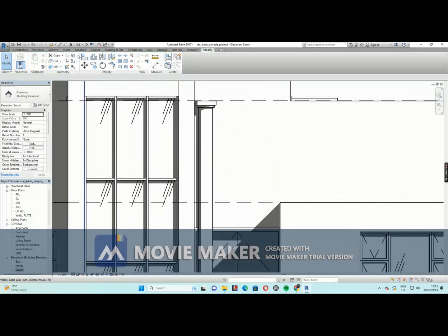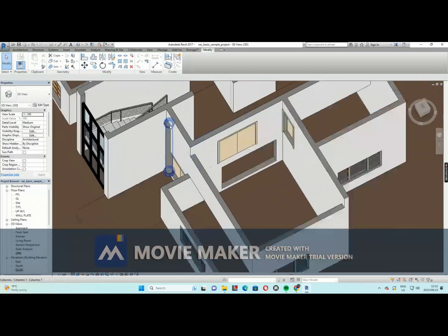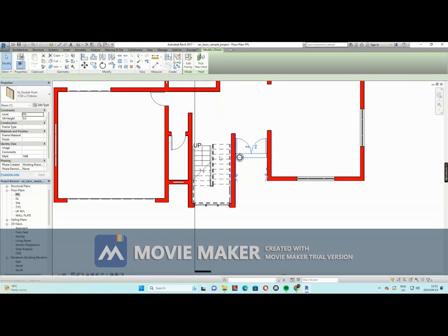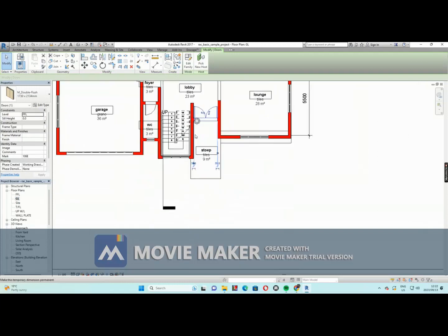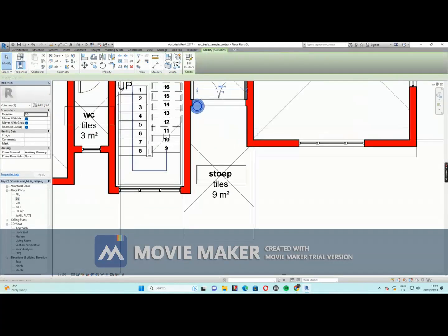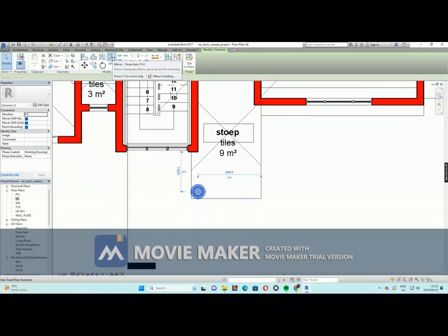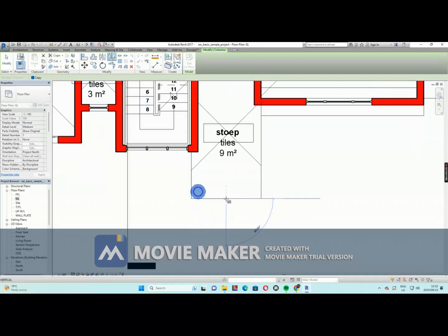Then you go to your first floor. You click your ground floor. You click here. You remove it. Now you want to move sideways only. So what you do is you copy. You put, then you move. Maybe I want it here. Then this one you delete. This one you mirror. Mirror, draw axis. My midpoint for this wall is here. Then I go down. I mirror. I've got a column. You see? I've got two round columns.